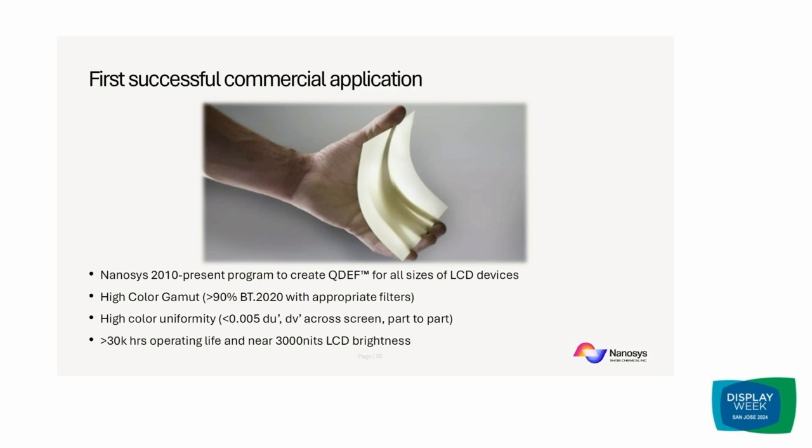The most obvious advantage you can see with QDEF in a display, if you have a side-by-side comparison, is the really high, wide color gamut coverage that you can see with quantum dots. Again, if you pair that with the correct color filters, you can have 90% coverage of BT2020 color space. And not only that, it overcame all of those other issues that I was describing before. So color uniformity and defects were no longer an issue.